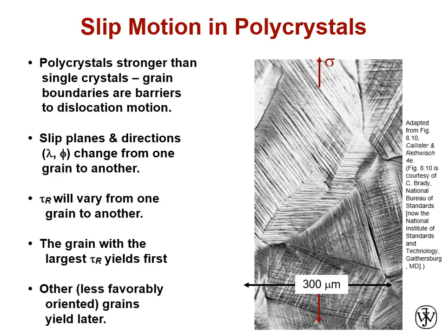Now we have another effect coming into play. We can get those dislocations within each grain moving, and they will move first depending on the orientation of our slip systems relative to our applied stress. But they can't move forever, because dislocations encounter quite a barrier to movement when they hit a grain boundary, something we discussed in our defects discussion. So each one of those grain boundaries is going to be an inhibitor to dislocation movement.